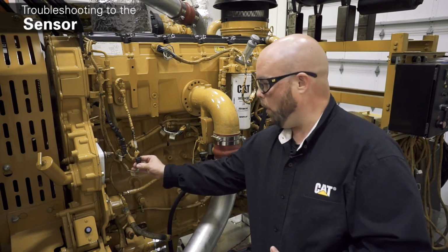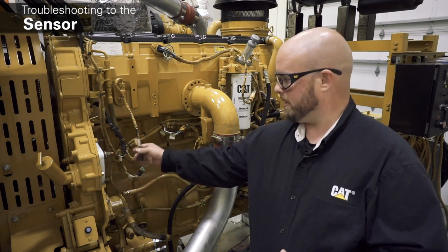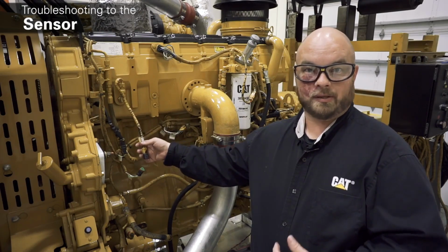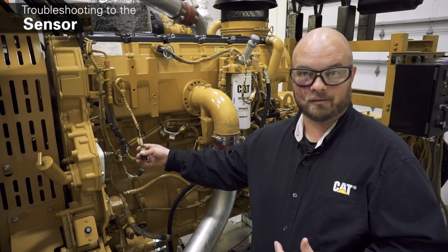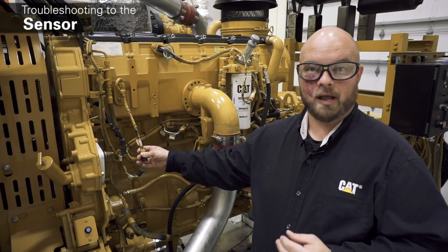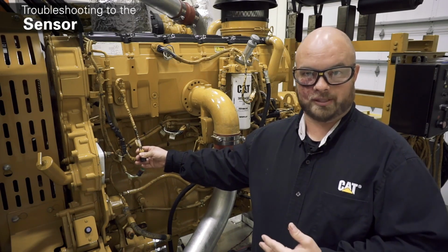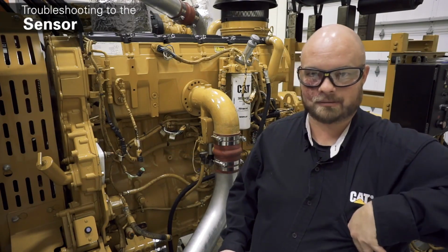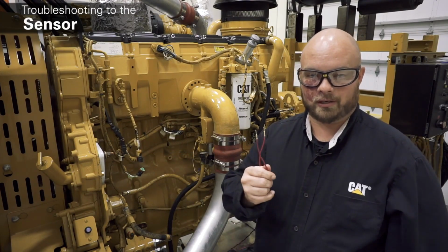So if I open up our sensor here, he's completely out of the equation now. The opposite condition of a -3 code is a -4 code. That is an FMI -4 code. That is a voltage below normal condition. I can make that happen, okay? And how am I gonna make that happen? Magic. A little short jumper wire here, okay?